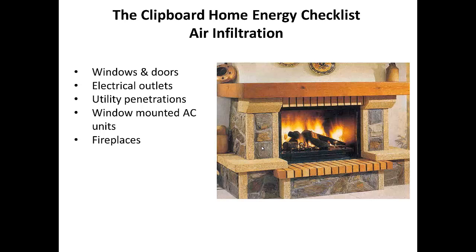Now, on my fireplace, because I knew back in 1978 when I built my home that a fireplace is made of stone, can anybody tell me what type of heat losses would be caused by that stone? You would be having conduction losses through that stone, because stone is a lousy insulator. So when that stone, if it's on the outside, gets cold, it's going to pull the heat from the inside right out. So that's conduction losses, or the heat traveling through a material itself.